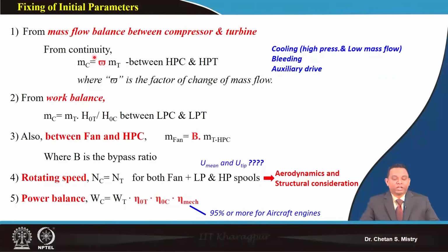The reason the mass flow rate going into my turbine will be slightly different is that a fraction of the air, highly compressed air at slightly high temperature, is injected at the HP turbine for cooling purposes.